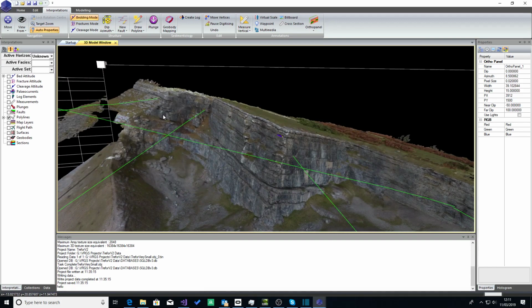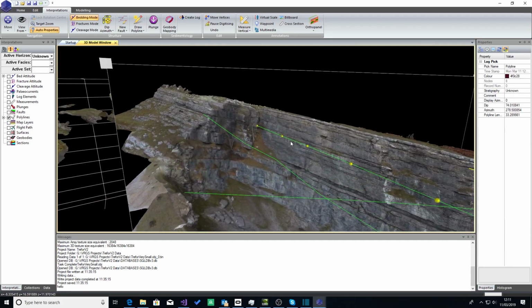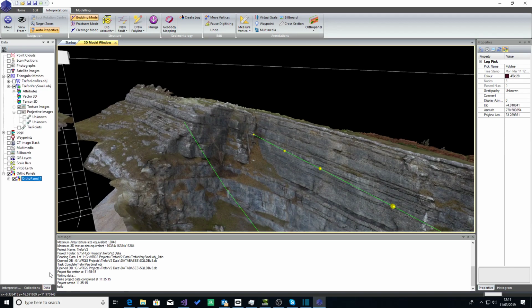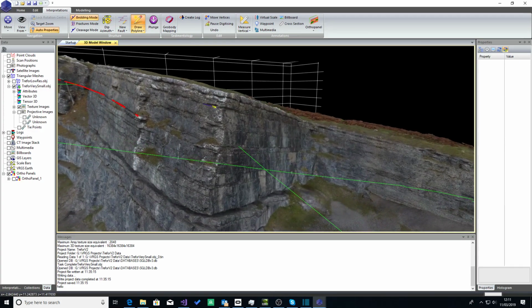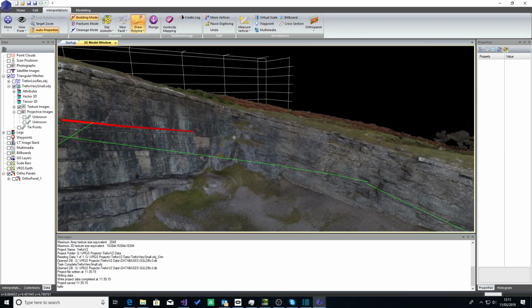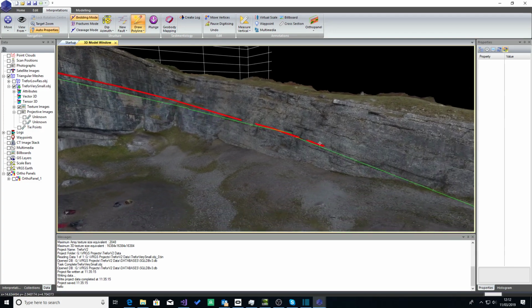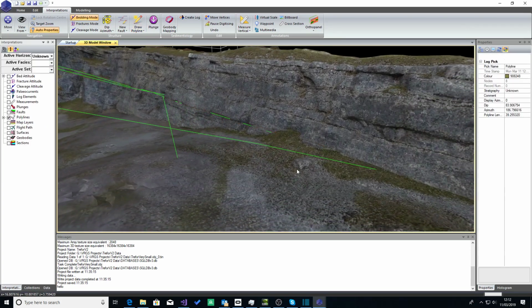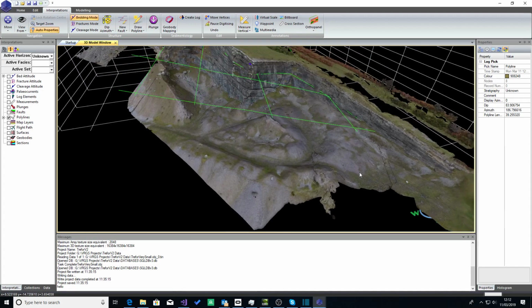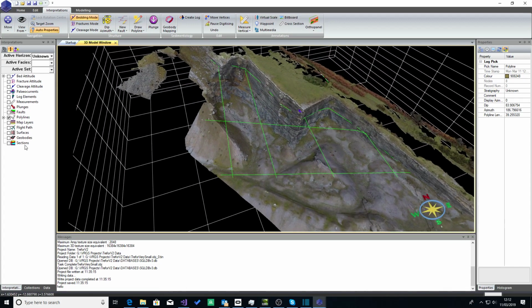So we can then take this to this stage where we're looking just at the 3D model. I'm going to switch off my orthopanel, and then I'm going to interpret. Remember, shift while you're interpreting. Pause is interpretation, allows you to move and navigate. And there's the end. So I've now created a set of polylines which are delimiting that surface in 3D.